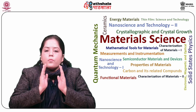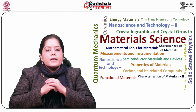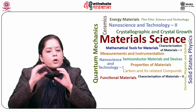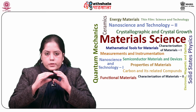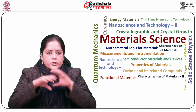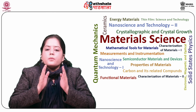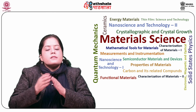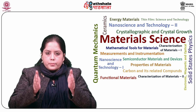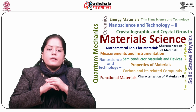One of the most popular techniques using this approach is lithographic patterning, where a short wavelength light source is used to create the desired structure. Its main advantage is that the pattern as well as the objects are created at the desired place and no further assembling is required.